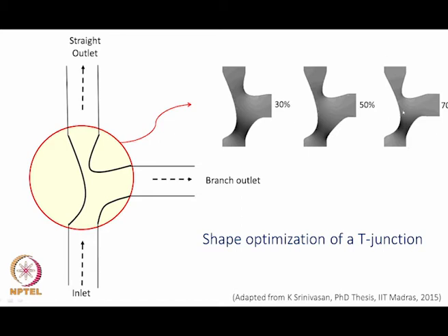And what are we doing here? We are creating a constriction here. We are necking this region by changing the shape in such a way that more of the flow is going through this and less is going through this. In fact, if we do not have any of these controls, if we just have straight sections here, 90% of the flow would go through the straight section and only 10% would come through this. So if you want more flow going through the outlet, you constrict the flow so that you direct it to go into this.